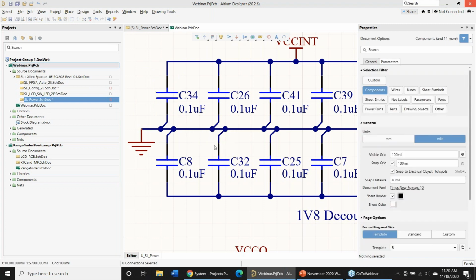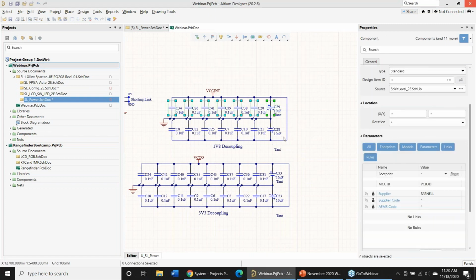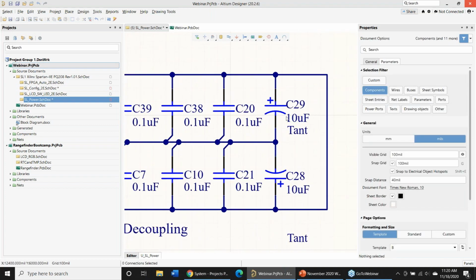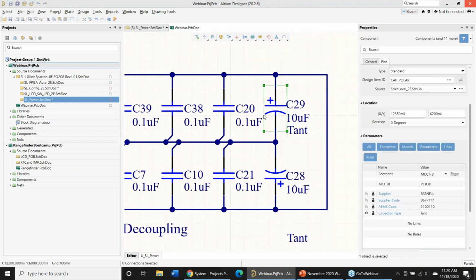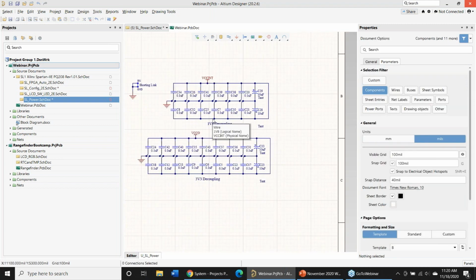So I use that all the time when I grab things. Since I only have components, I can grab all these at the same time. I can hit the shift key, grab all these at the same time. I don't have to worry about completely covering the part. I can just come in here and barely touch it, and I get this part. So that's the left-right selection feature, and it works quite well.